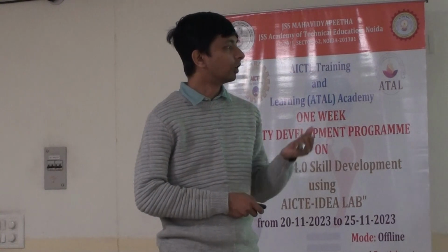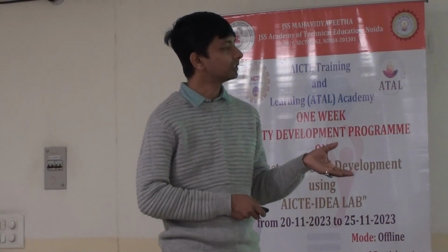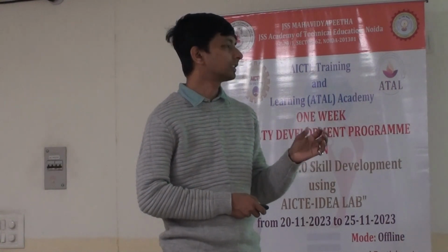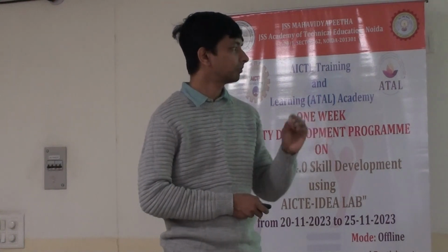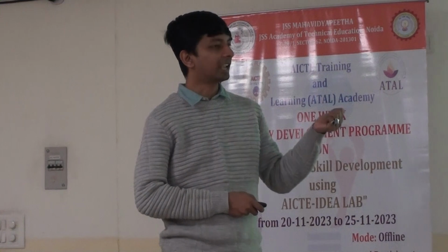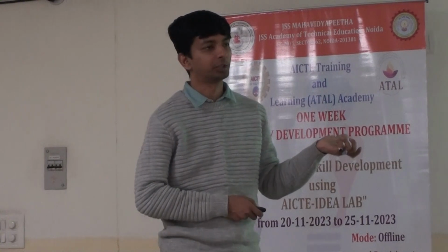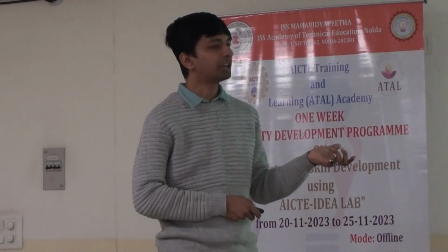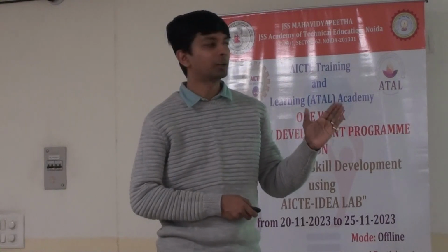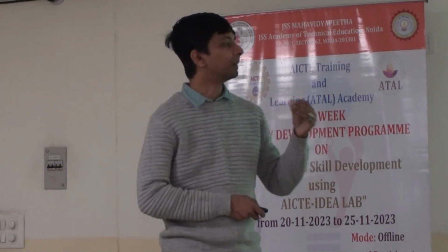What oxygen does is cause an exothermic reaction, and by that process the required energy density will be relatively less. If you are not using oxygen, if you are using nitrogen, you can also perform the laser cutting, but your energy requirement will be relatively high. Oxygen is relatively cheap, so why use nitrogen? You use oxygen and take the advantage, because here we are not bothered about the oxidation of the material. Here we want to ensure that the kerf width, that is the cut width, is minimum, and how best we can utilize the laser to melt the material and blow it away.